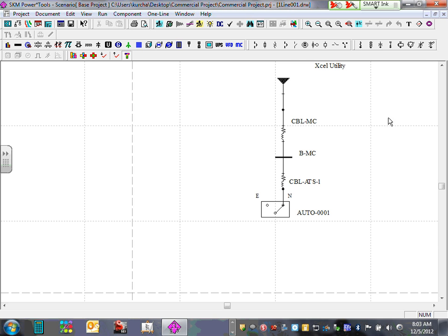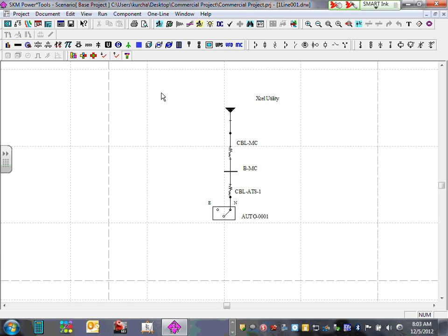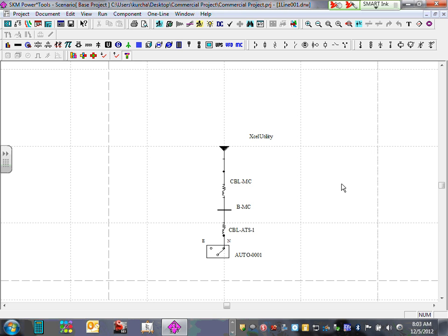Can you select everything and move it? Yes, thank you. Select all the stuff like in CAD, box them in, and hover over them, Jeff, until you see that cross. Can you see that cross? And now you're holding the whole thing and moving it in your hand. Everybody can see that? You can move it anywhere you want. If you want to move anything, you have to select it. It becomes blue. Hover over it. You see the cross. Then you can move it. If you want to move the tag, select the tag only.